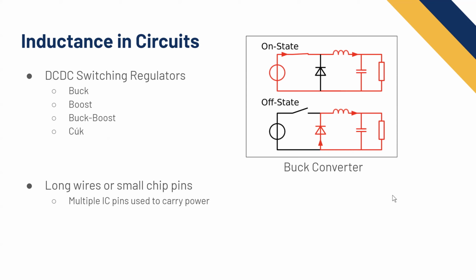But once again, inductance, how it manifests in bad ways. If you have really long wires, that wire is going to have some inductance and it's not going to want the current to change. That's just a characteristic of conductors. They have some inductance, and the longer it is, it sums in series. So longer wire, more resistance, more inductance, not great.